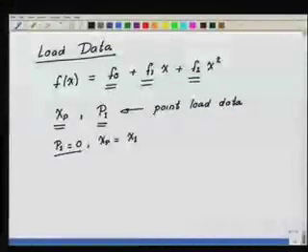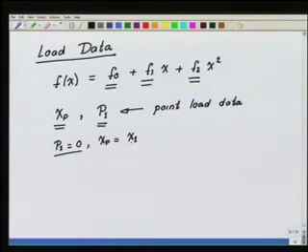Okay. Now if I don't want a point load, then I will set P1 equal to 0 and I will set XP equal to X1. So what I am doing is making this value 0 and moving the point where this 0 load is applied, which is meaningless, to the end of the domain, just for our convenience. You have to remember that when P1 is equal to 0, I will have to set XP equal to X1. We won't give XP equal to some point in the interior of the domain. So this data is available to us.